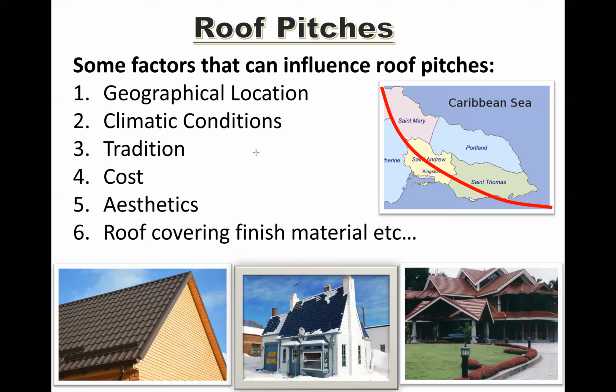If I were to draw a steeple, let me just draw a line, and say I'm using wooden shingle or clay tile or whichever. If you were going to make it steep, then you can reduce the lap to a shorter distance. But if you are going to make it shallow, then you would have to increase the lap.